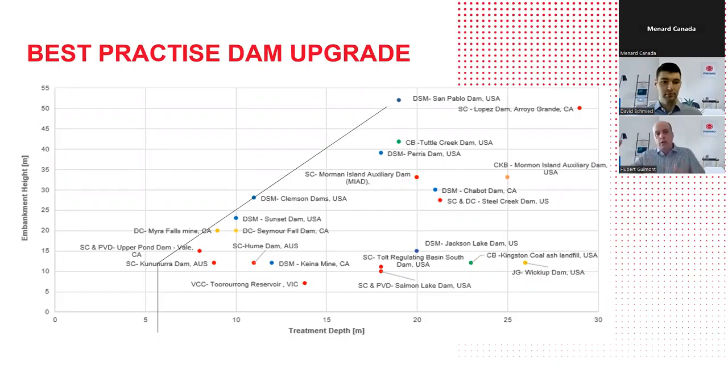And as the treatment depth and also the embankment height increase, designs typically require more shear strength resistance, and it goes more towards soil mixing applications.